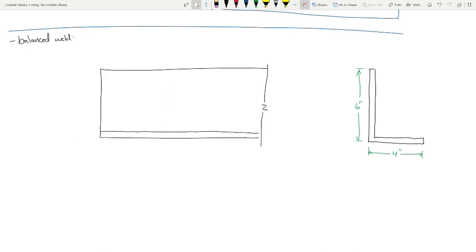Okay, now, help me out. This is an angle, right? So I'm going to be applying a load of 150 kips. But in a balanced arrangement, I am assuming that that load goes through the centroid, okay? So the centroid is going to be right about right here. So we'll draw it like this. So probably what I need is this dimension right there. Now remember, keep in mind, this is an L6 by 4 by 3/8. So let me put that right here.